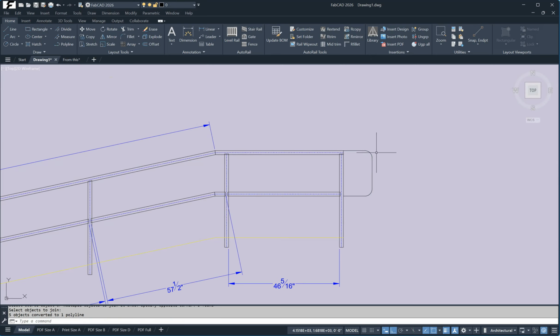Then it's 1.25" schedule 40 pipe. So I'm going to offset this connected loop now 1 inch and 5/8, or 1.66. So I'm going to do offset. And the offset distance is 1.66. Hit enter. Offset here. And there's my loop.